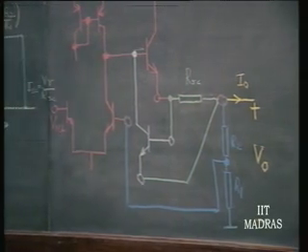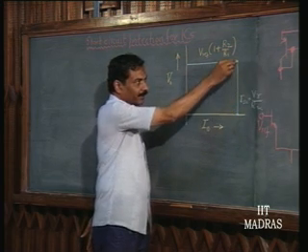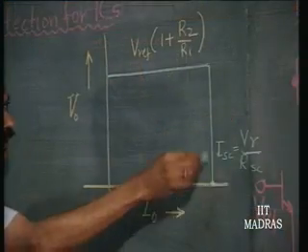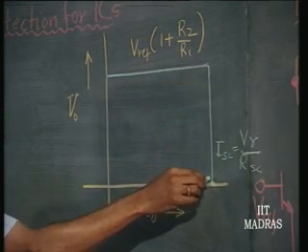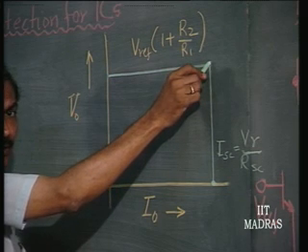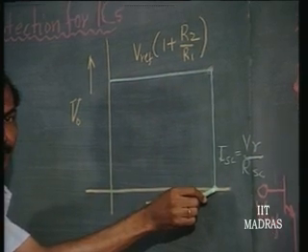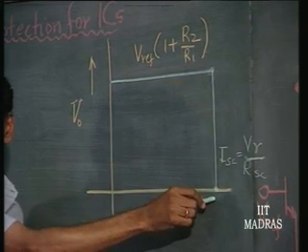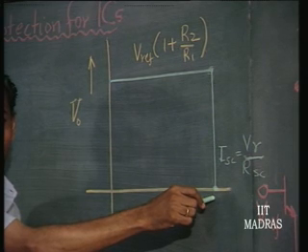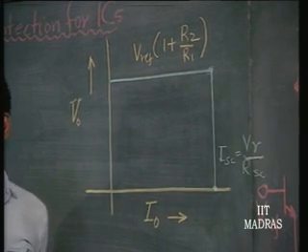Now, that kind of short circuit protection results in the voltage source being converted into a current source thereafter, and therefore the current is going to remain constant. We found that the power dissipation under that situation in the IC is lowest at this point, but highest at this point. So it gradually increases from this point to this point, and nobody can guarantee us what exactly our short circuit situation is going to be, and therefore this kind of situation is not a good thing for